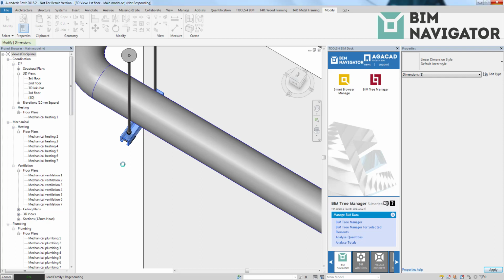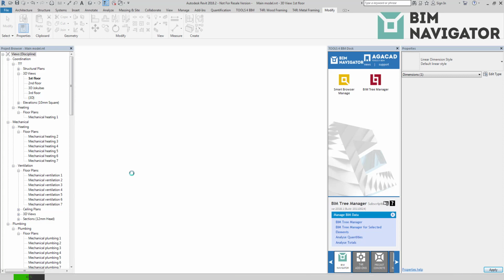So I'm gonna just show you what I'm speaking about immediately. So I add 10% of length for each of the families, and I put that into the parameter. Once I used that for radiator heating, because by the regulations we have to add 15% per each radiator. So I just calculated the room heating load, and I added 15% to that load. There are various ways to calculate something.